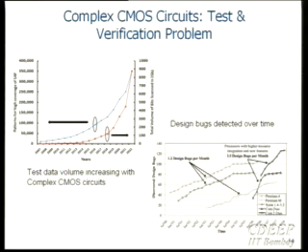Just to make sure that you have very high confidence that your circuit works, you have to apply a good number of test vectors, right? From a layman's point of view, if I had 100 inputs to a circuit, and if I need to verify, at least from the functional point of view, that it really works, and it's a combinational circuit, then I need about 2 to the 100 vectors, right? If you think of applying 2 to the 100 vectors to a circuit, and one vector takes 1 microsecond, that's going to take you years to test one circuit, right? So that's not a way that you can really test your circuit.